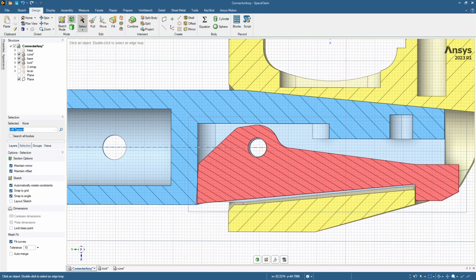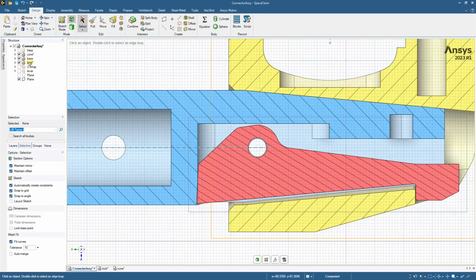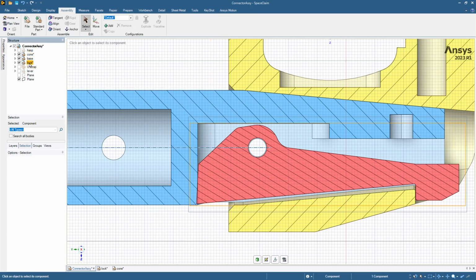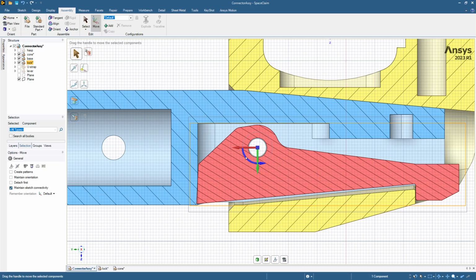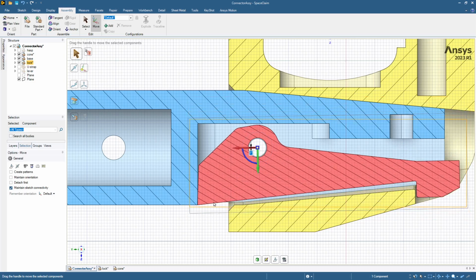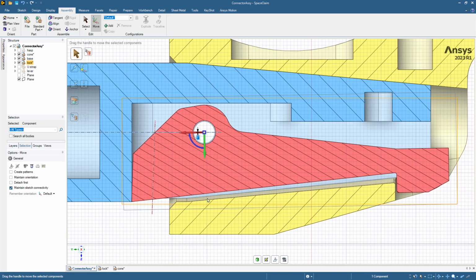And we need to resolve that, but when we rotate the component under assembly, or select components, we want to select the lock and do a move on that. Now we only need to rotate about 1 degree. I'll just do that, 1 degree. So 1 degree resolves the interference, but the point here is that this improved design has caused less motion and the locking function is more secure in this design than the original design.